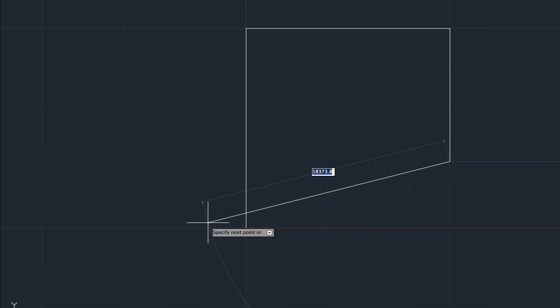From here, we add our second vertical line. As it goes down, the value of the angle changes from 90 to 270 degrees. Type in @10,000 with 270 as an angle. We now move on to the second horizontal line. As the line goes from right to left, rather than left to right, the angle is 180 degrees. We therefore type in @10,000 with an angle of 180.